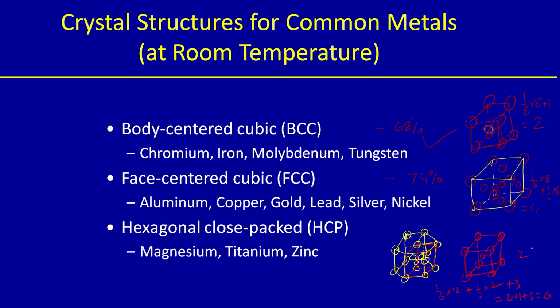Hexagonal close packed structure is close packed again, it has 74% space occupied by the atoms, and only the remaining 26% space is vacant, just like a face centered cubic structure. And many of the important metals, magnesium, titanium, zinc, as well as many ceramics crystallize in this, like aluminum oxide, which is one of the important ceramics that forms a hexagonal crystal structure.